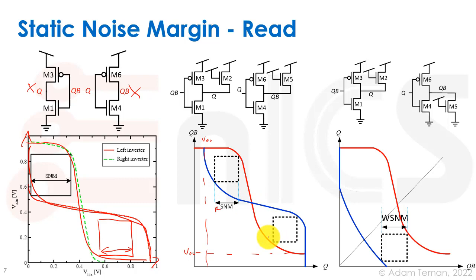On the other hand, with write, we get again this other type of parallel scheme over here, as we saw before. But with write, what we want to do is disrupt the bistability of the cell. So we do not want our cell to have these 2 states, either a 1 state or a 0 state. We want to ensure that it gets only to the 1 state that we're writing to. So we want to bring this to this state. We don't want to allow it to come into some other state. So we want to break the bistability. How do we break the bistability? We pull this blue and this red curve away from each other, and we get something like this.